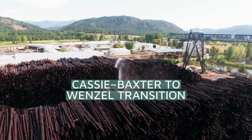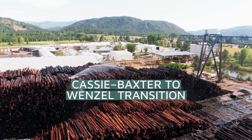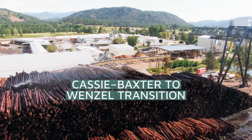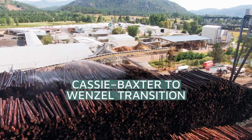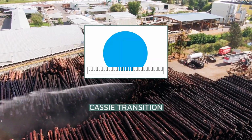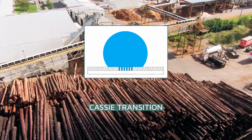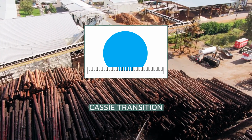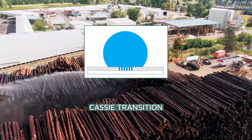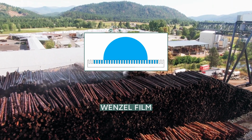Cassie-Baxter to Wenzel transition. In the Cassie-Baxter model, the drop sits on top of the textured surface with trapped air underneath. During the wetting transition from the Cassie state to the Wenzel state, the air pockets are no longer thermodynamically stable and liquid begins to nucleate from the middle of the drop, creating a mushroom state as seen in Figure 10. The penetration condition is given by cos θ = (1 − φ)/(r − φ), where r is the solid roughness for a flat surface.